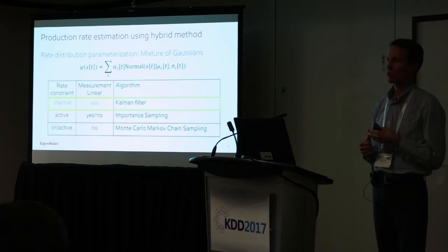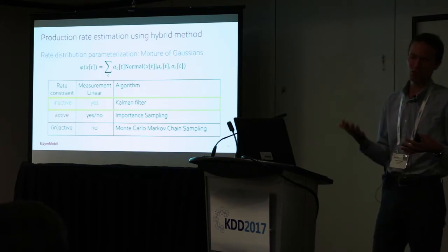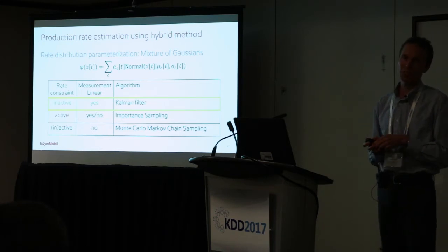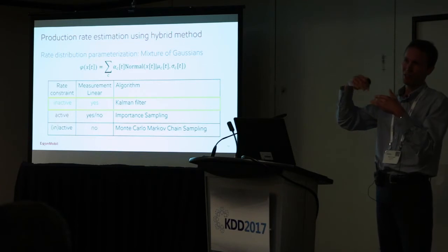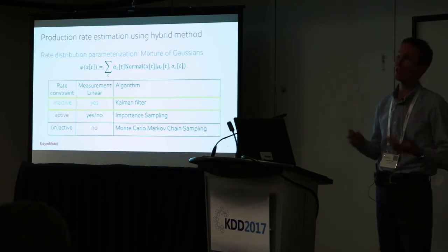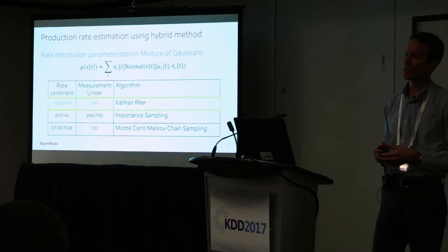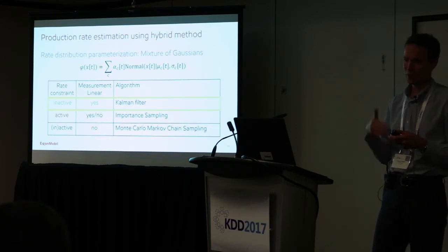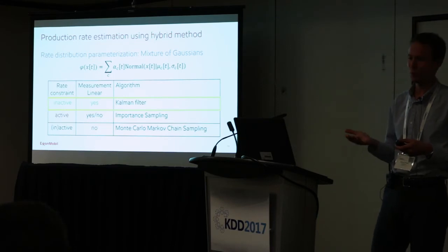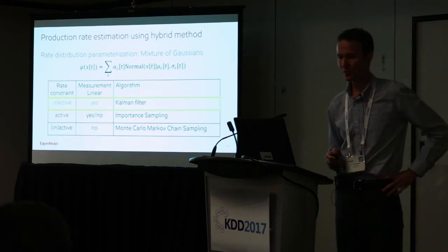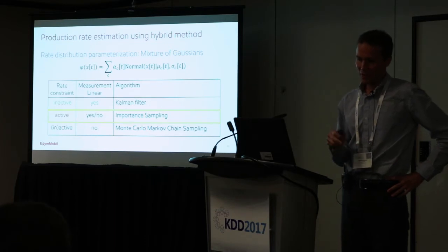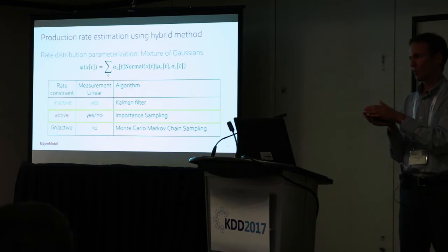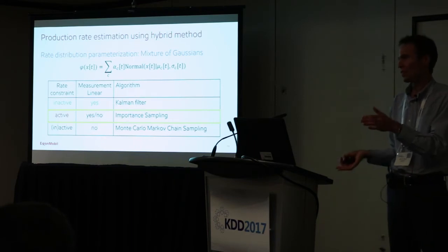So for example, the liquid rate is just the sum of the oil and water rate, so that's linear in the parameters. The only one that's not linear is this water fraction measurement. As the word says, it's a fraction, so this is a non-linear measurement. But we don't have too many of those. So in this situation, we can do very convenient, very low computational effort computation.